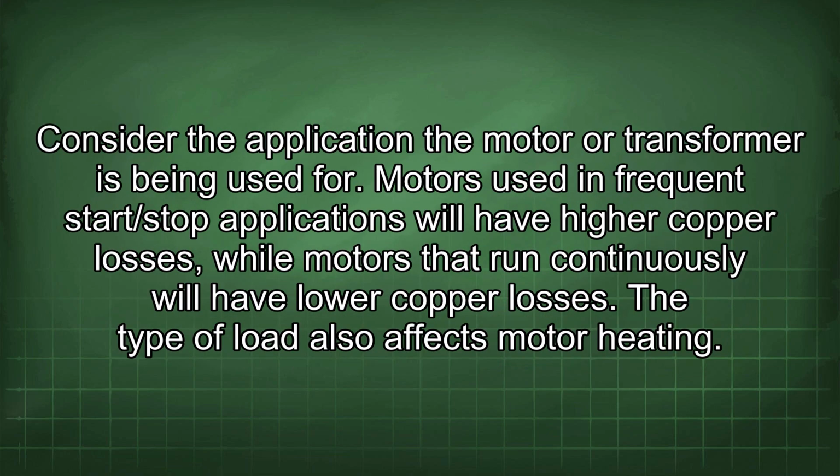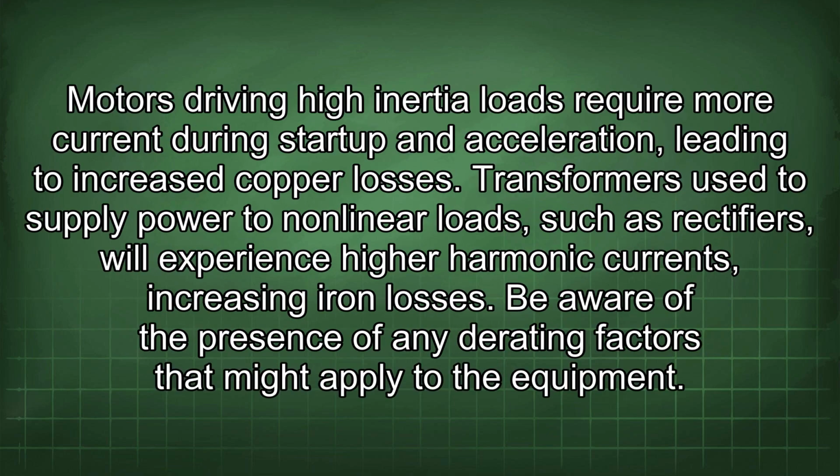Consider the application the motor or transformer is being used for. Motors used in frequent start/stop applications will have higher copper losses, while motors that run continuously will have lower copper losses. The type of load also affects motor heating. Motors driving high inertia loads require more current during startup and acceleration, leading to increased copper losses. Transformers used to supply power to nonlinear loads, such as rectifiers, will experience high harmonic currents, increasing iron losses.